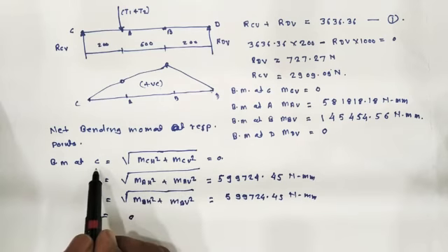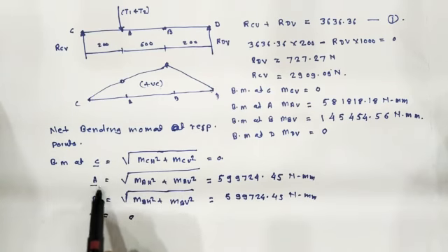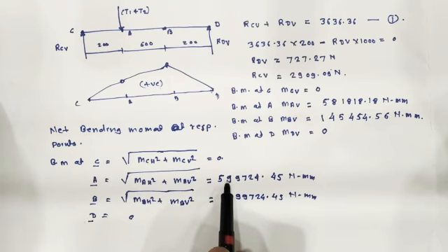After calculating the net bending moment at the respective points, fortunately here at both locations A and B we have the same value of bending moment, because of the same diameter of the pulley at the same distances.